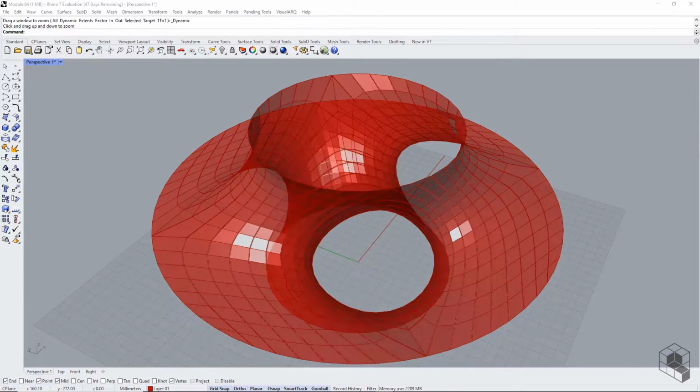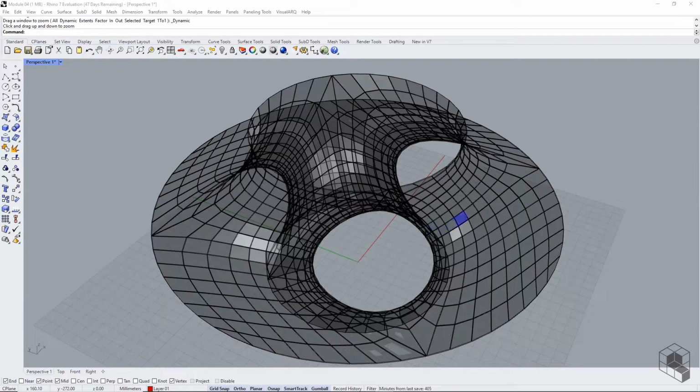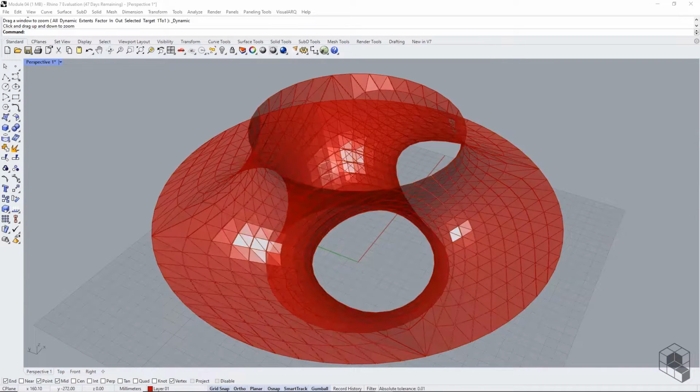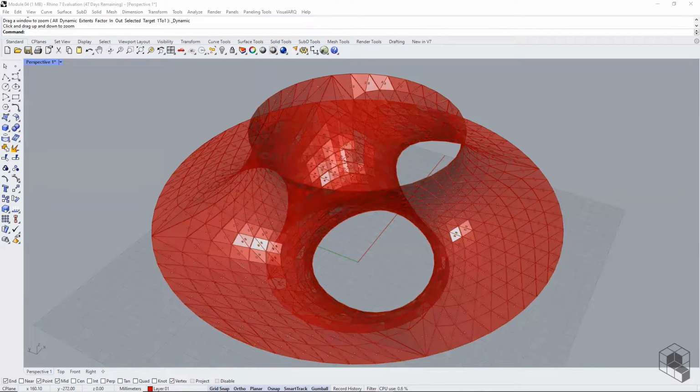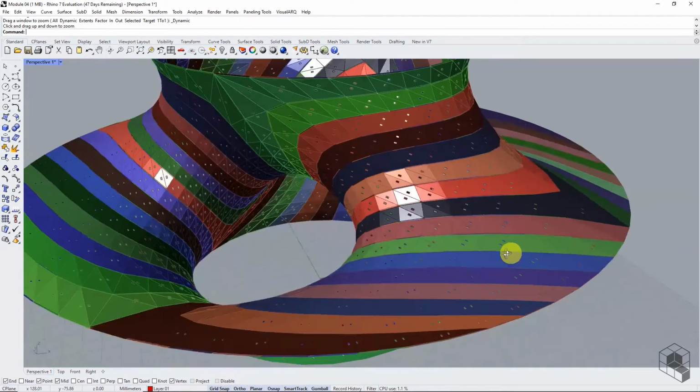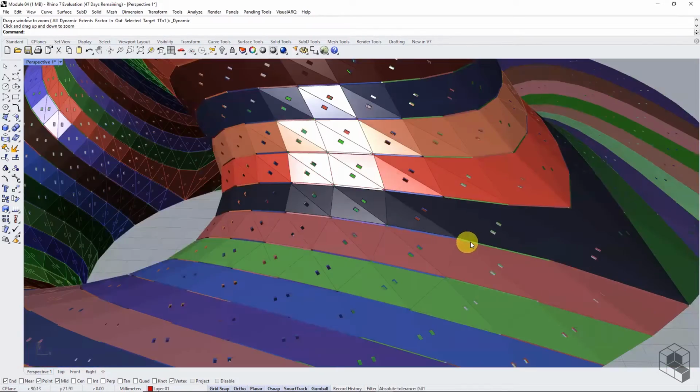Let's understand the logical workflow before we start building the script. First step in this process is the grouping of identical quads from warp weft strips. Once grouped, these quads will be triangulated to ensure that both quads have the same diagonals. Slots for cable ties will be created by intersecting extruded rectangular profiles crossing through both quads of the same group. Once we have the triangular faces with slot profiles, the triangles will be clustered as per the original warp and weft strips. Let's start building the script.